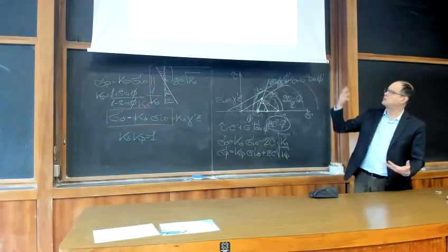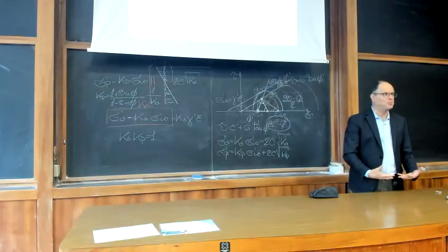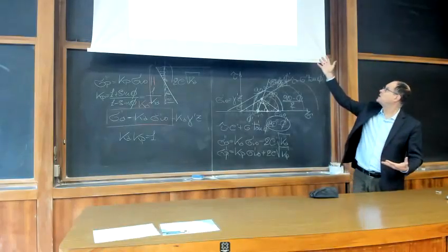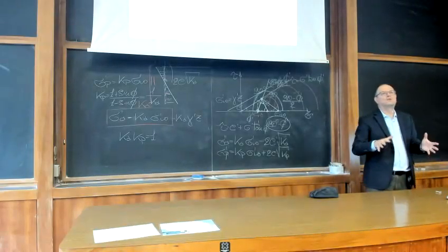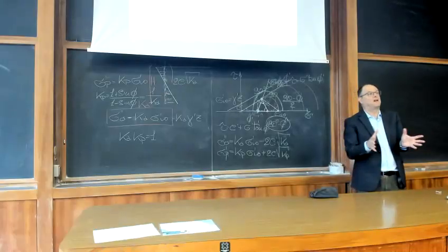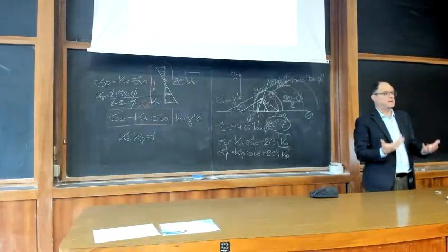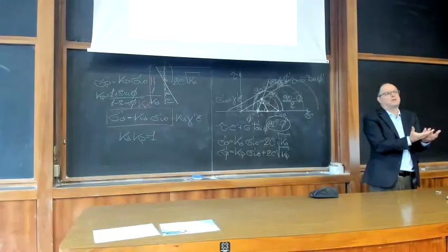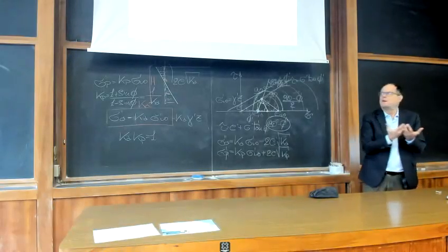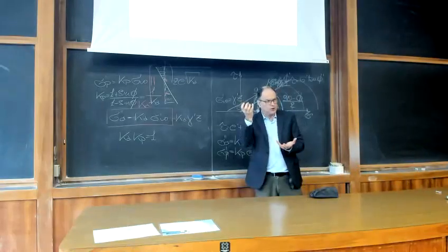Now this is not realistic. Of course, we know that the foundation at some stage will stop, but once you reach very large settlements, you consider that the soil has failed, that you have reached the bearing capacity of your foundation. The bearing capacity is the maximum capacity of your foundation. But the bearing capacity of your foundation does not depend only on your foundation.